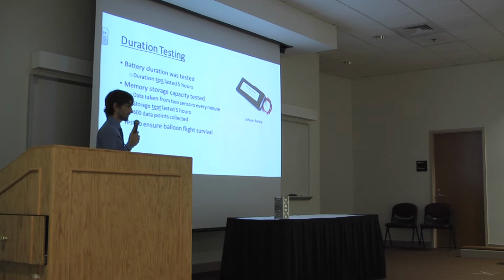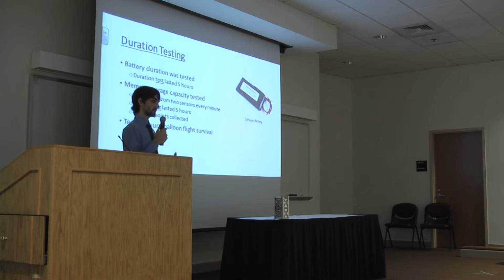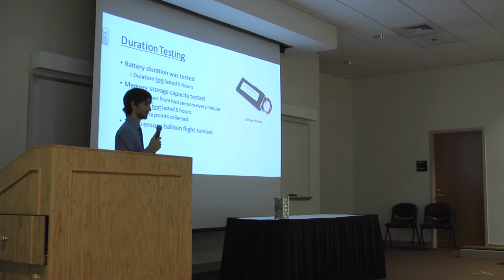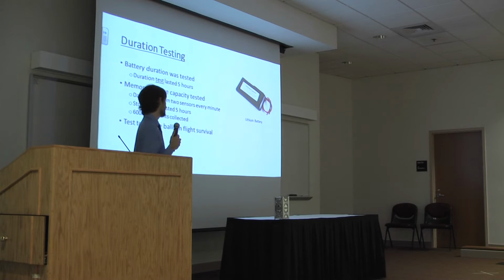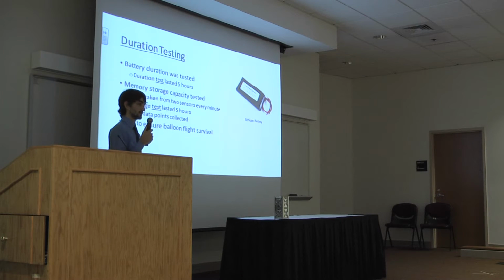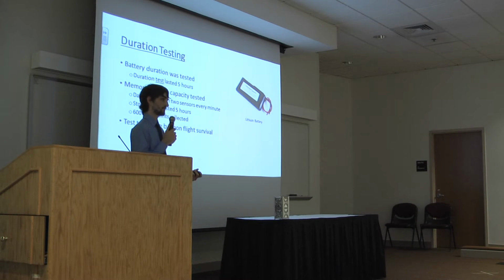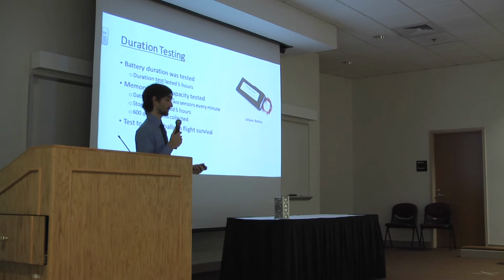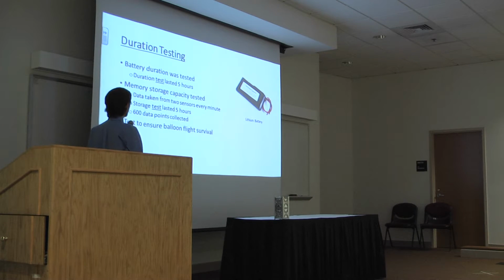The duration test, what I did was I plugged one of the batteries into my subsystem to make sure it would last the duration of the high altitude balloon launch, which is roughly 2.5 to 3 hours. So I plugged it in for 5 hours and it collected 600 points of data, and the memory was not full and the battery did not die, so it was going to work for the high altitude balloon test.